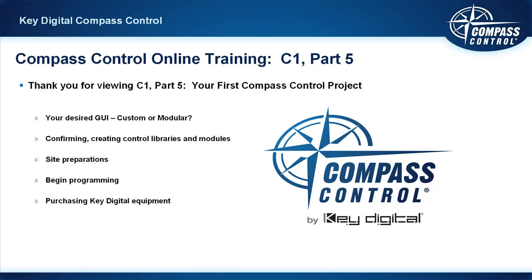Next, confirming and creating the control libraries and modules. So you know what you want it to look like. Do we have those control codes for all of the devices you need? If not, refer to the C2 training videos to create your own libraries, or if you want to just edit a module, we'll continue with that here in C1. The site preparations and checklist on the site: all of your connectivity and wiring, is that all laid properly? Are things connected properly? Is the network healthy, or are you dealing with a network where you have one main router, but then you move 50 feet away from it, and it's half the signal strength, half the bandwidth passing, right?